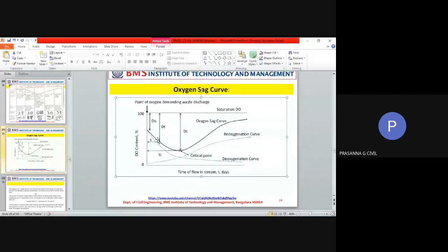So when you say saturation DO at 0 degrees, you will have the maximum DO dissolved in water. And you know that in tropical countries like India, our temperatures will never reach 0. Maybe there are countries where that is the case. So these are two very contradictory terms that we will be using. You can imagine a place where the temperature is so cold, 0, because the temperature is low, the dissolved oxygen concentration is very high. But at such a low temperature, how many organisms will be active to do the degradation work? Understood? That is contradictory to the amount of DO present.